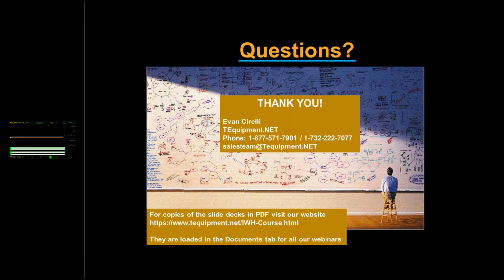We can do power analysis. We've got a histogram. We didn't use a zone trigger on these signals today, but you have a nice graphical zone trigger you can use just with your finger on the touch screen to capture signals that way. And so really the ability to use all those different capabilities. We talked mostly about the different ways we can use the memory in single capture or in segmented memory. And then additionally, the search mode capture.